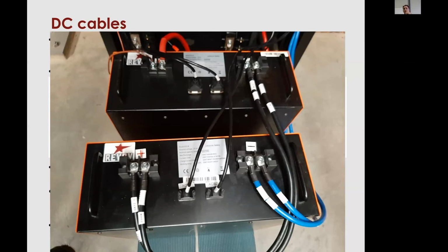What I mean by favoring the battery: if the DC circuitry is a little bit out of balance, in other words, one of these, either negative or positive, is at a slightly lower resistance, you will end up drawing too much from one battery on a discharge, as that dam effect or that wear effect comes into play. And then when you're doing the recharge of that battery, the opposite battery is favored over the lower one.